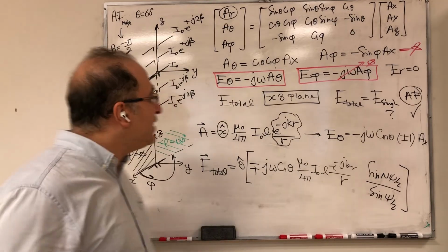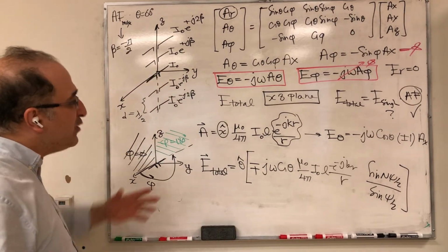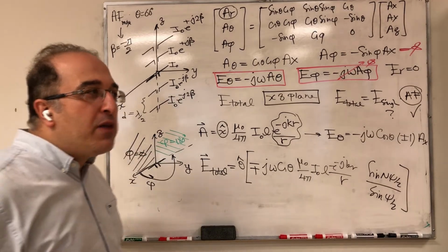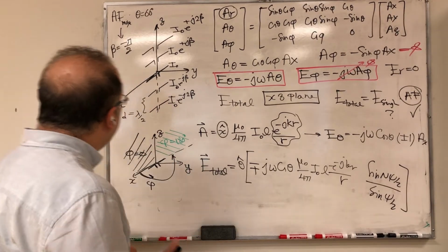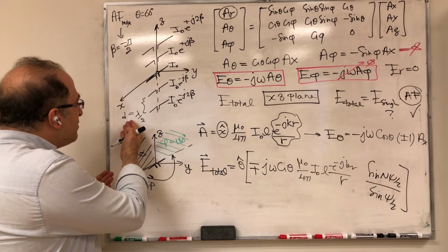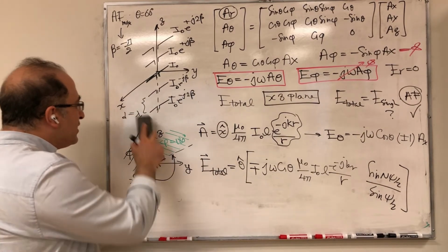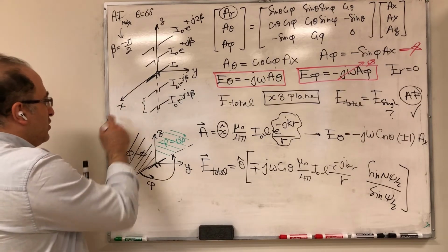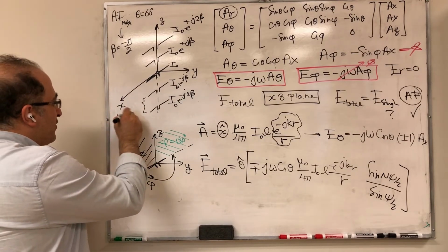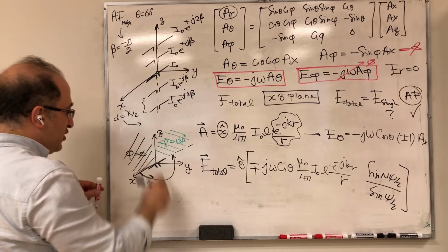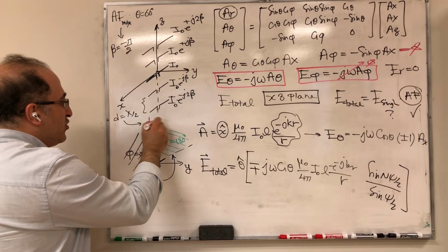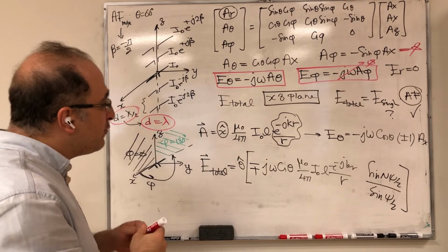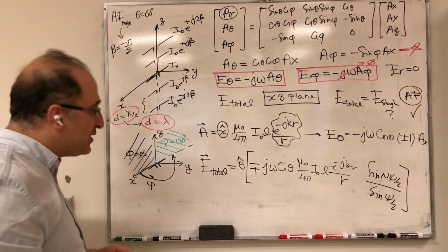And the nature of the mistake is the following: you do everything based on the assumption that d is half a wavelength. But the person who fabricates it makes a mistake, and instead of half a wavelength, the distance changes to just one wavelength. So from here, you go to here. Of course, you finish your design and your beta is minus 90.